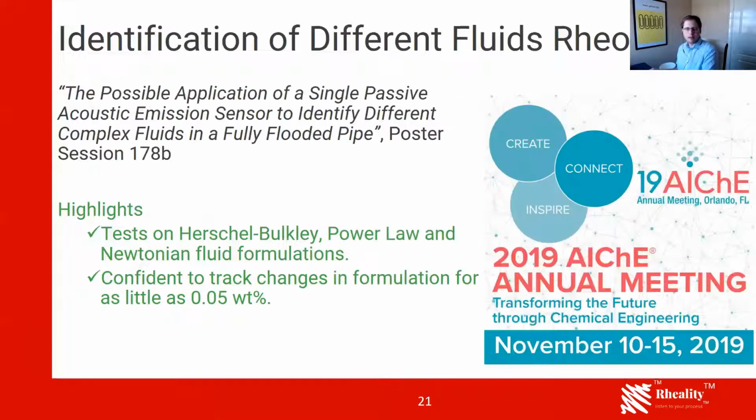So, current and future developments. Last year we presented at the annual conference in America from the American Institute of Chemical Engineers. We had a poster presentation. We tested complex fluids falling into a Herschel-Bulkley relationship and power law fluids, such as soaps, for example, and determining fluid formulations. And what is that the resolution, while we are very fine, is we actually track formulation changes of 0.05% weight percentage difference. And we could potentially go lower, but that's the lowest we can do in Birmingham with our testing so far.